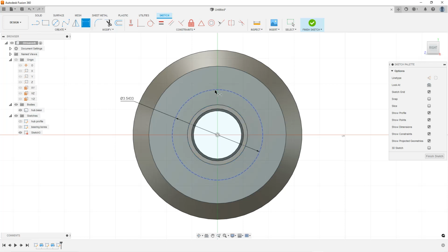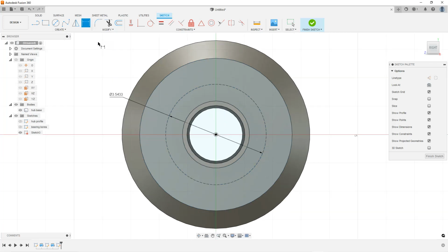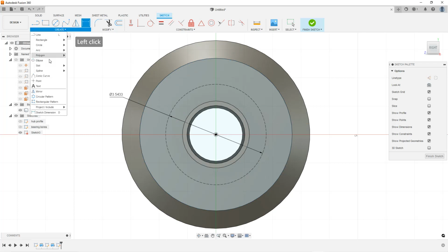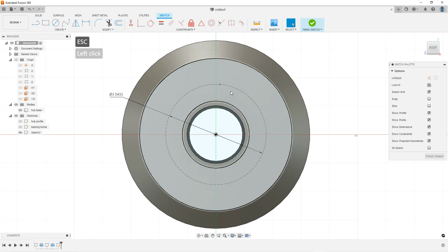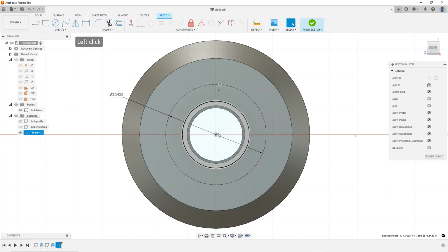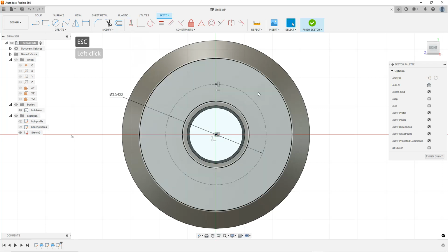And what I want to do is create 5 points on here, and I'm going to use those points to locate our threaded holes. So if I go in here and just click point, I can then put a point on the circle. And the first point I want to start vertical from the center line. So clicking that and the origin, and use the horizontal vertical constraint.